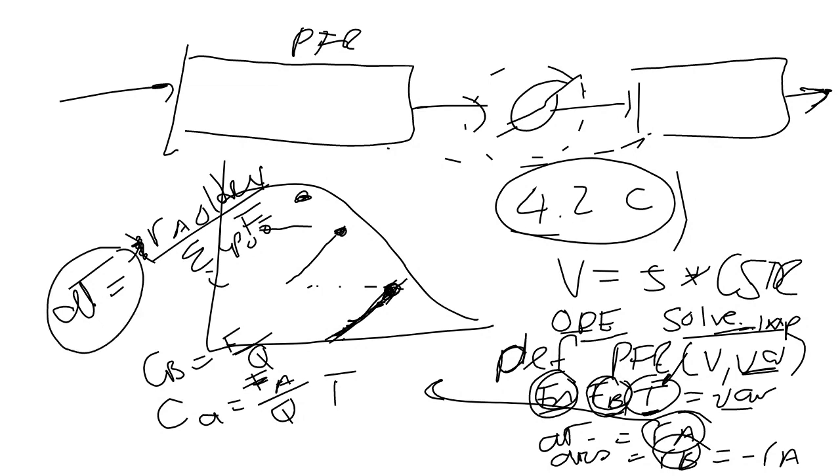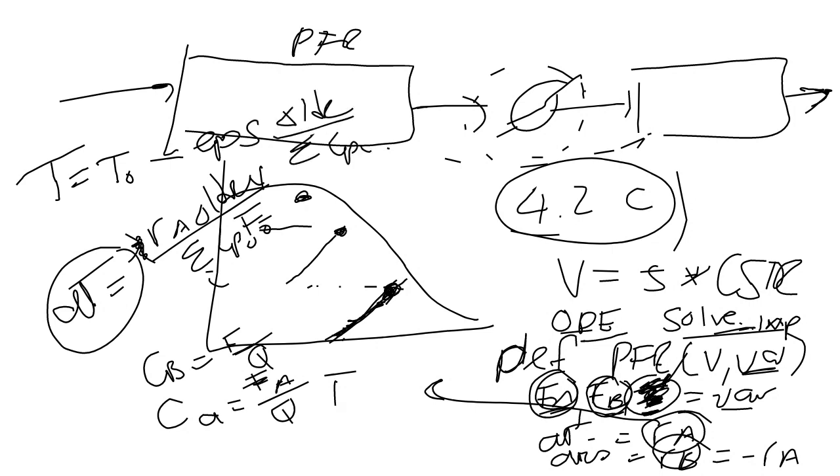Or you are not going to have this as a variable, but then for each FA you are going to have to calculate that temperature using T equals T naught minus epsilon ΔH reaction divided by the sum of those heat carrying capacities.